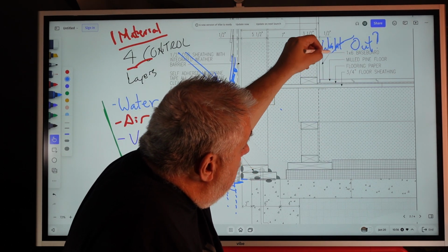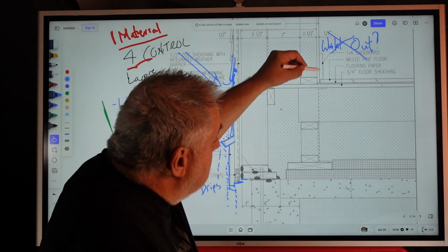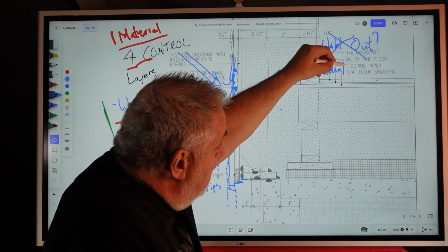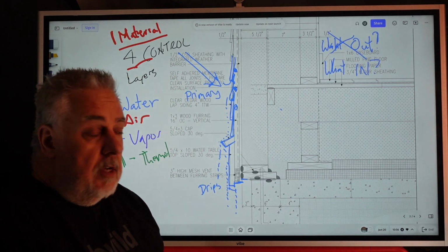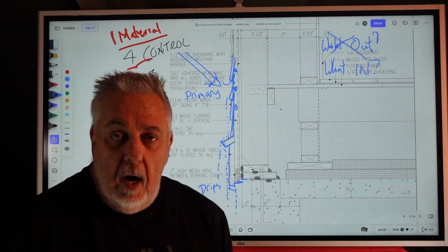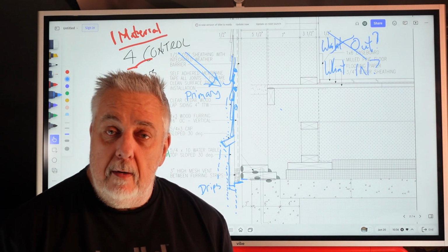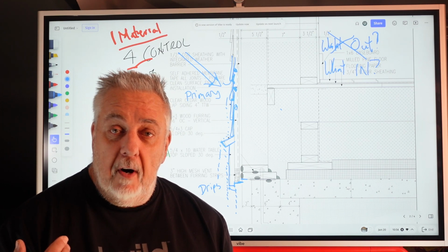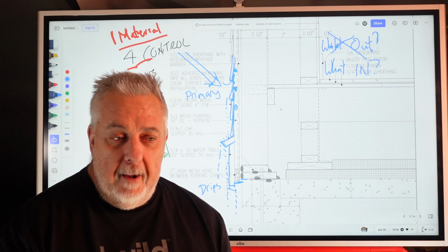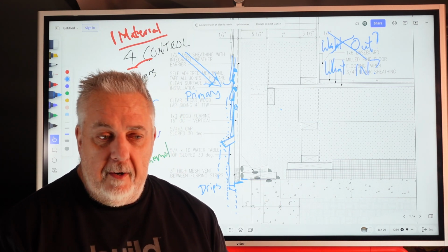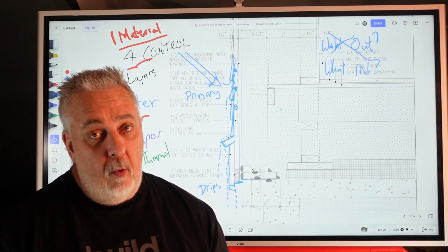No, you are at a loss if that's what you believe. The real question there is, what are you sealing in? So you put sealant at every one of those lap siding joints or at the ends, and water gets in, guess what? It can't dry out, right? And when it comes to moisture and vapor, and you'll see when we talk about it, it's on a scale of I need to be able to dry more than I wet.